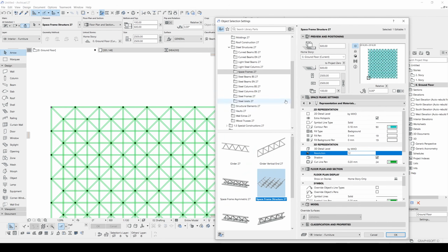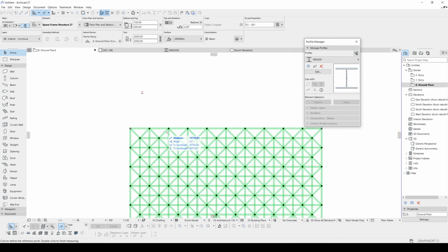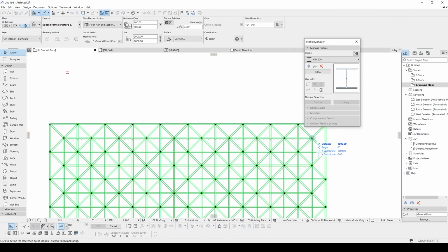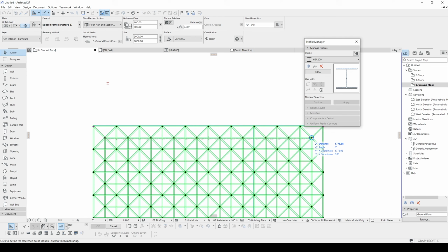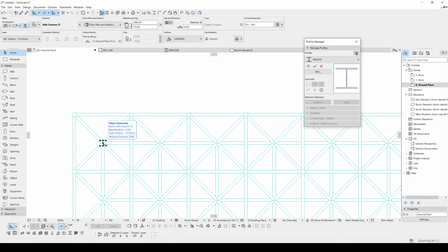Therefore, I'm going to go to settings, make this 2000, and after that from the main settings we will see the distance between the axes has been changed. It's 2 meters right now, and if I hit M from here to here, it's 1800. So if we divide this by three, our grid distance will be 9 meters. So it's easier for now.